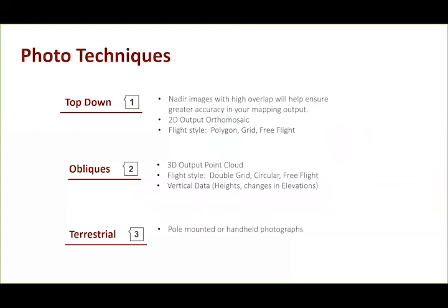Terrestrial, again, nothing says that you can't. A lot of the photogrammetry software allows you to bring in photographs that were captured in different methodologies. So if you have a handheld camera or a pole-mounted camera of some type where you're, say, documenting a vehicle at a tow yard where maybe you conducted an initial flight of a circular or orbital pattern around it at different altitudes, you can additionally supplement that with another camera that's handheld, with or without GPS, or on a pole mount to get some good vertical angles, and integrate those with your drone data that came from an aerial flight.